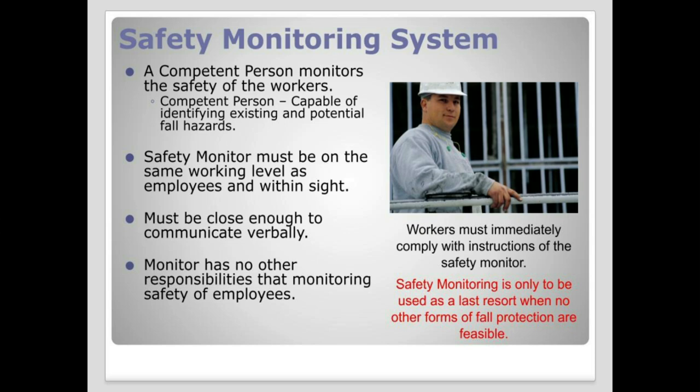Safety monitoring system. A competent person monitors the safety of the workers. The competent person is capable of identifying existing and potential fall hazards. The safety monitor must be on the same working level as the employees and within sight. Must be close enough to communicate verbally.